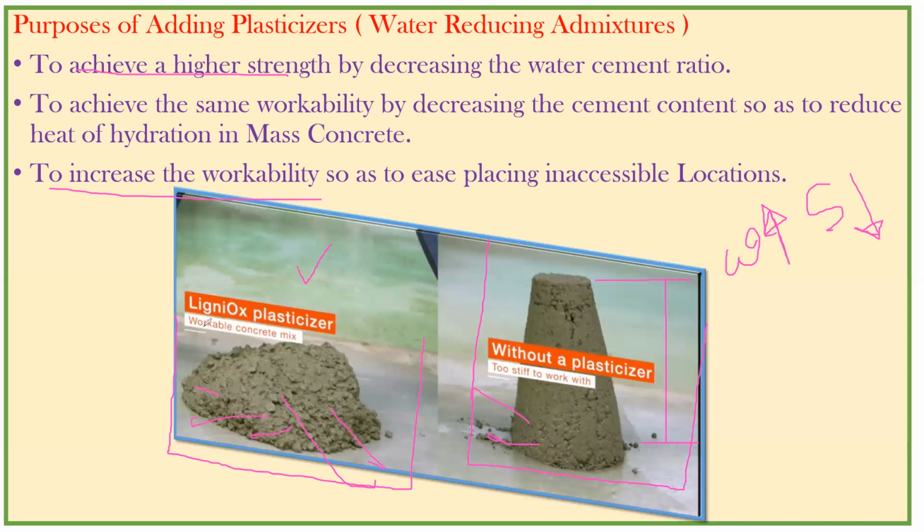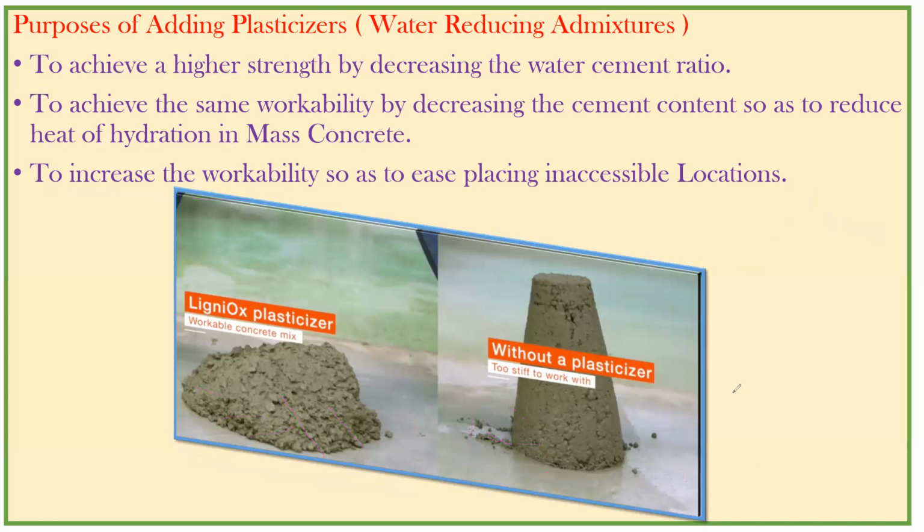So it's written here, workable concrete mix, and it is too stiff to work with. With the help of a plasticizer, we can increase the workability, or we can even decrease the water content for the same workability.